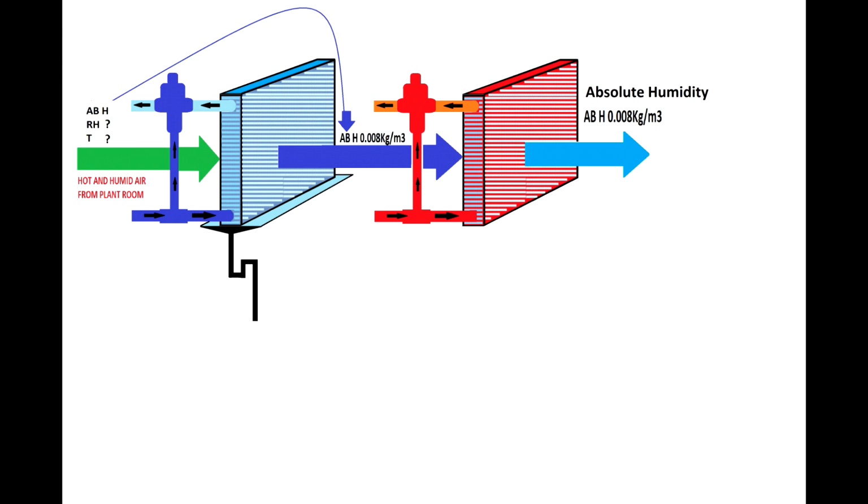I have observed on many occasions that people focus more on the heat exchangers or on the glycol temperature or the glycol flow through these heat exchangers, but we have to consider the airflow through these heat exchangers, and we don't have to push through a heat exchanger more air than is allowed by its specification, because it will reach a saturation point and won't be able to do its duty.